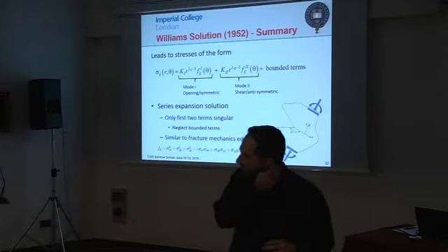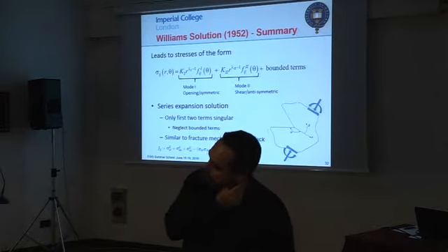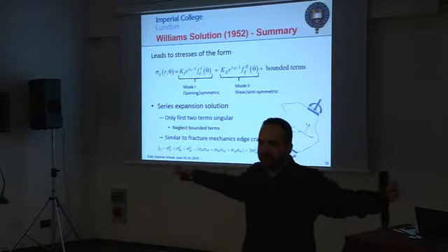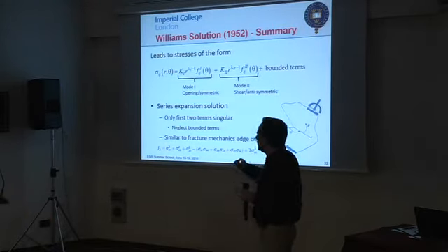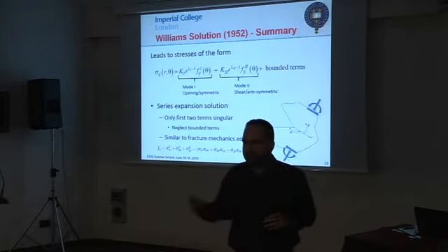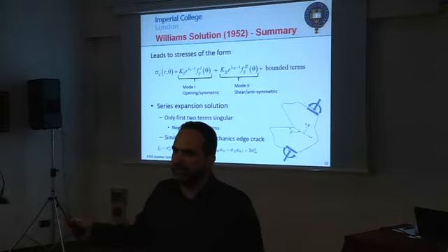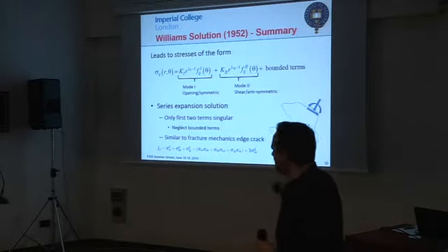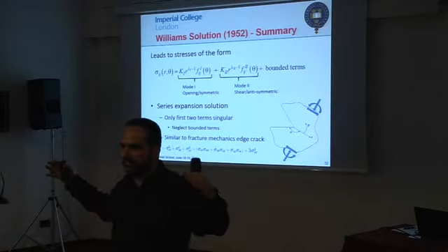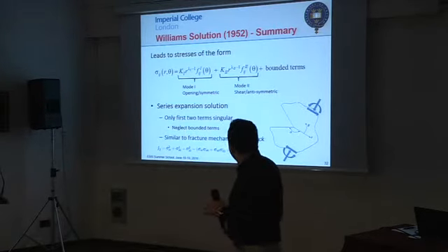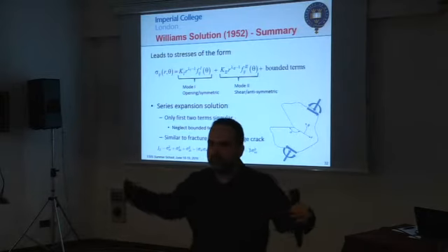Now all the terms we add to that are bounded. So it's like we're taking a series representation of the stress and we're saying these two are the dominant terms, especially in some regions for a certain alpha. Now, obviously, that is not the full solution. If you keep looking outwards, other terms will come in to describe the full stress field.